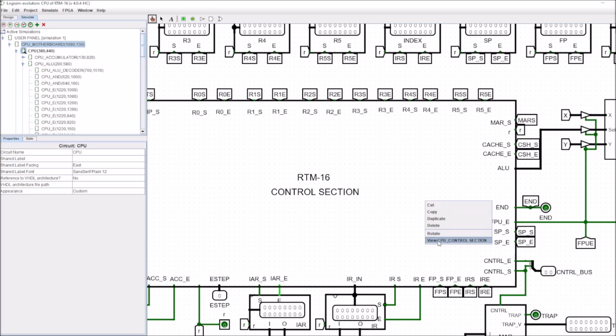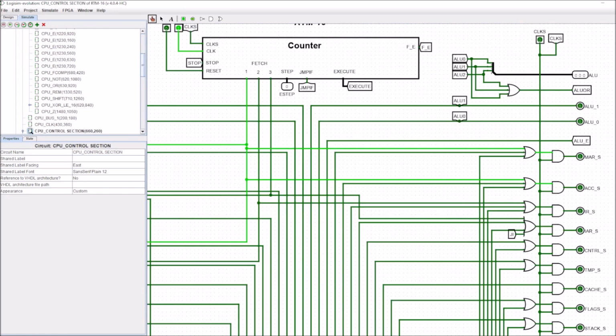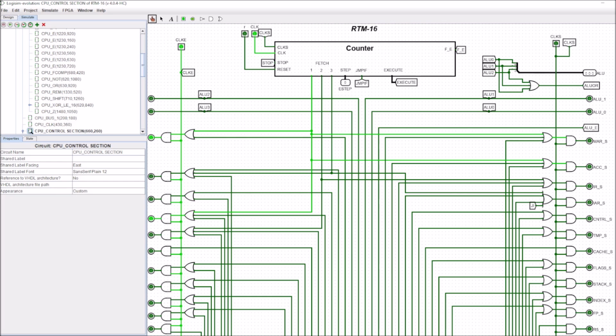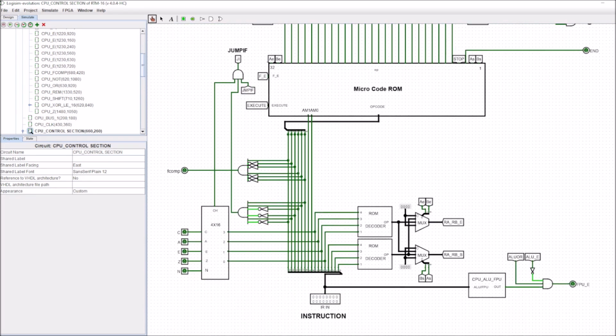So whenever we drop down into the control section, the first thing to note is that we have to be able to recognize a floating point unit instruction. So when we generate the instructions, we choose the floating point unit instructions, so we get one after another, and let's say they're in between two particular values. So if the instruction comes in here to the instruction register of the control unit, and if it's a floating point unit instruction, we can test for it here with this little test cell. So this is CPU ALU underscore FPU.